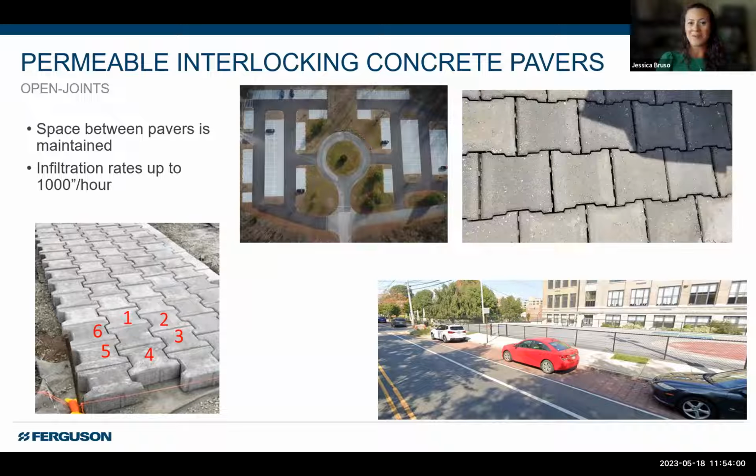These are actually about a foot square. They're 40 to 50 pounds each, so they are substantial. So they do not require sand in between to keep them stable. They are stable by interlocking with 6 other of these blocks, and of course a retaining curb there.